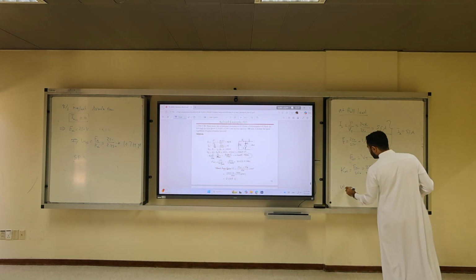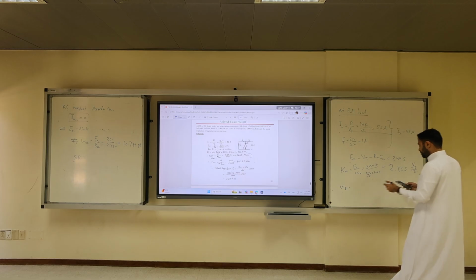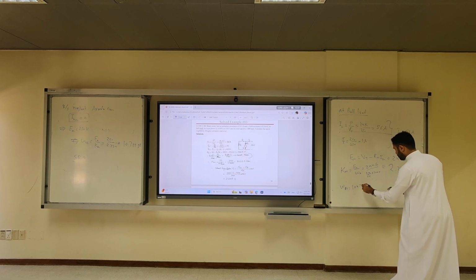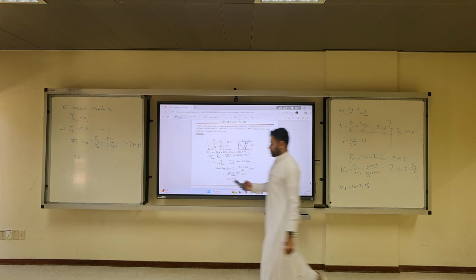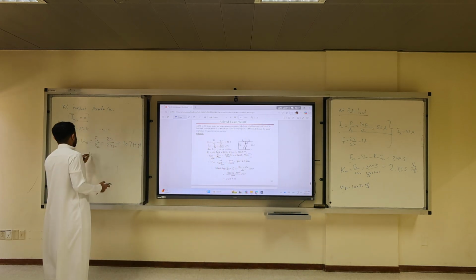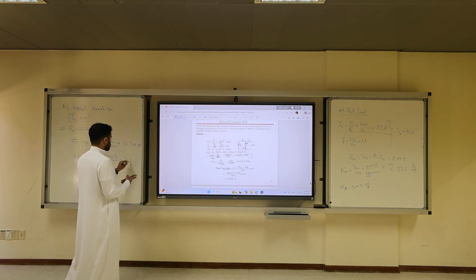What is omega full load? I forgot to get the number. 2 pi over 60 F. 104.72 radians per second. So it is 107.11 minus 104.72, divided by, is it full load? Divide by 104. So how much did I get? 2.29%.